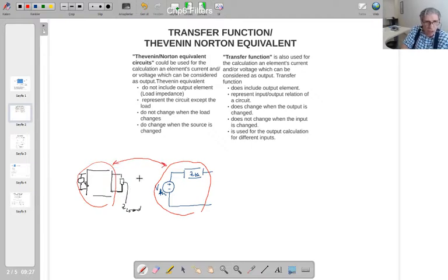And then we said if we connect to the terminals A and B here, they are equivalent. If you connect this load ZL here between the terminals A and B, we said this load current is equal to VTH over ZTH plus ZL, isn't it? So by using the Thevenin equivalent, I found out one of the element current and voltage of a circuit.